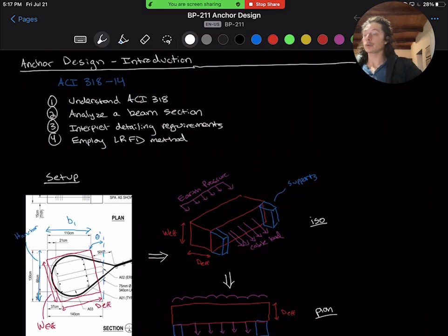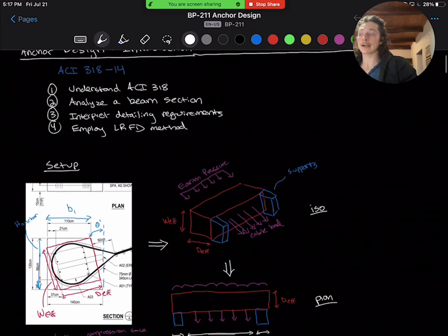And throughout this lecture, we will use the medium anchor, or the A2 anchor detail, as our example. So in the following diagram on the left, we'll estimate the beam section formed by the largest rectangle you can draw perpendicular to the loading. We'll call W effective the section width, and D effective the section depth. H anchor is the anchor height, and B1 is the width at the top of the anchor, as called out in the details.